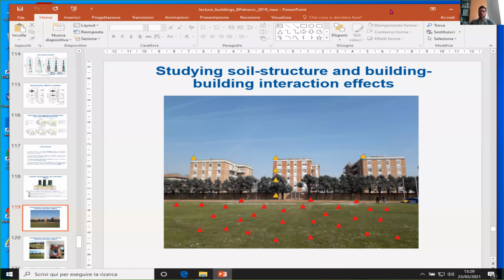So what you have seen as inversion of the dispersion curve, we would like to extend to several profiles using the contribution of all the modes. So we are now inverting for a large number of modes in order to improve the velocity profile that in turn is used in seismic reflection analysis for exploration.